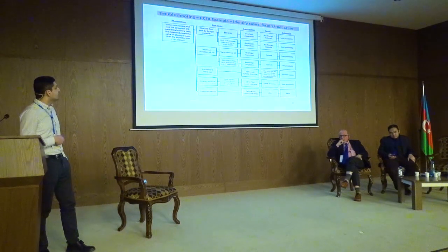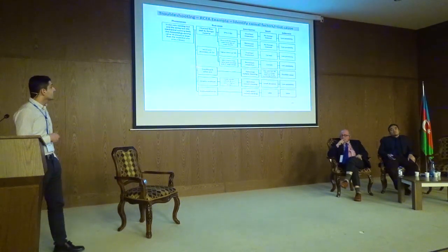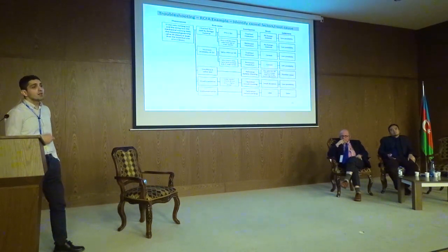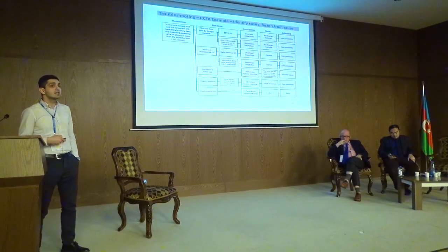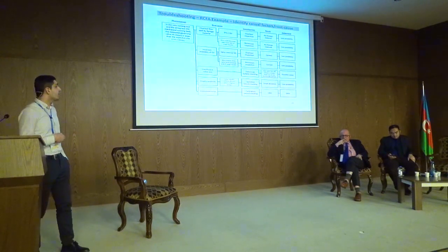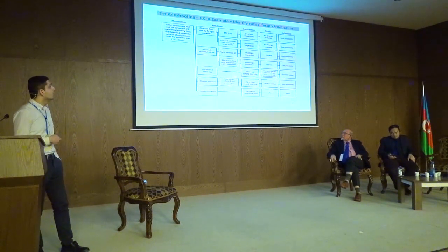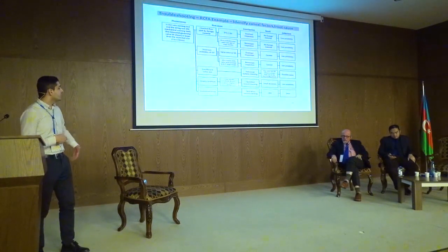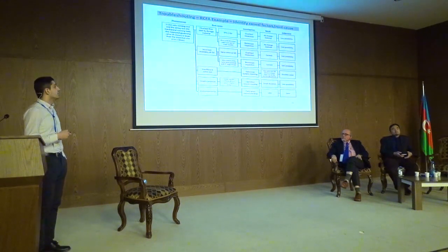After eliminating some other causal factors, we came to the conclusion that insufficient valve size was the issue. The valve was not chosen properly in the very beginning during the design stage. So this is a design shortcoming. Comparing to the steam turbines in other plants, similar steam turbines with the same power, the valve size was much less than it had to be.